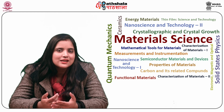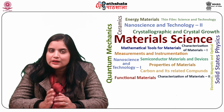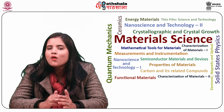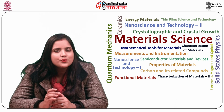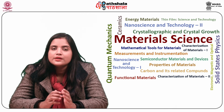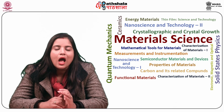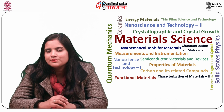Let us next discuss the disadvantages of the gas phase condensation technique. The products in the gas phase condensation technique, which are to be separated from the gas stream, have relatively high volume. Good filters are often required to do the job. Secondly, the process requires highly pure precursors, which may be expensive, as purification during the synthesis is not possible.